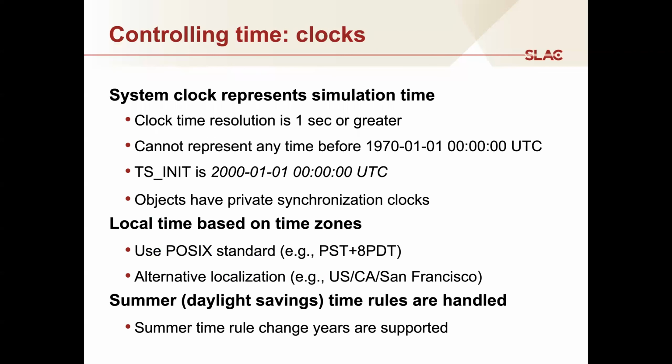Probably the next most important thing is the clock. As I said early on, Gridlab-d models a time series, what's called a quasi-steady state time series. And so we have to say when we want the clock to start and when we want the clock to end. And the simulation will advance through from the start time to the end time.